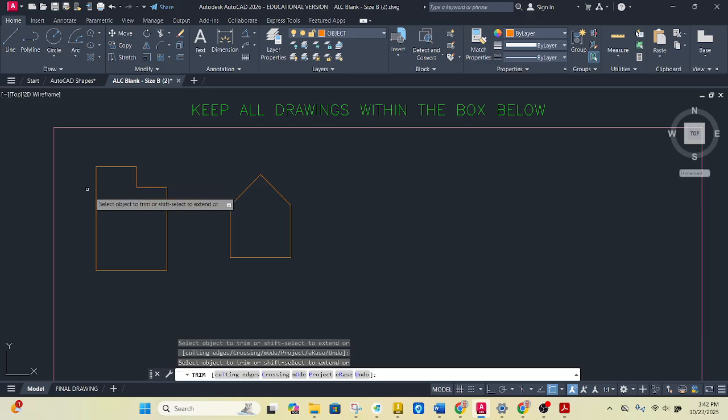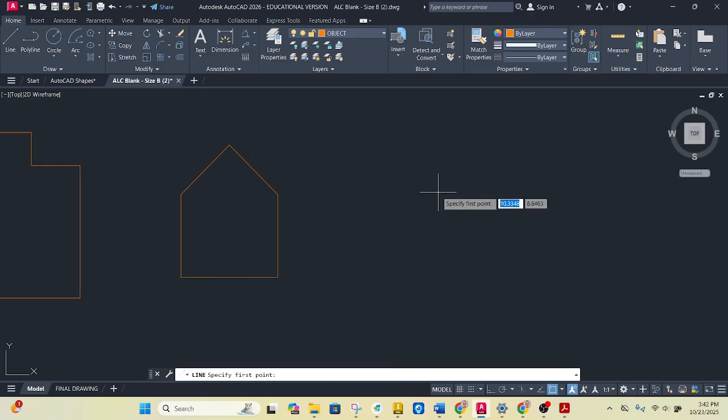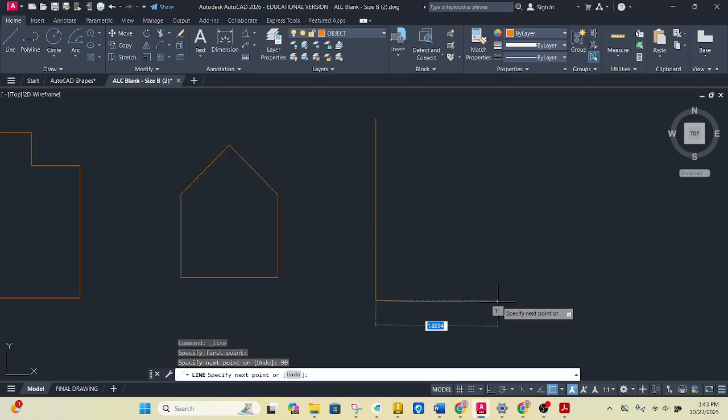All right, next one is the upside down Nevada shape. It's kind of similar where it has a length we don't know. So we're going to use that one last. So my first one's going to be at the top point. It goes down 2.75, tab, 90, enter. I'm just going to go this way.